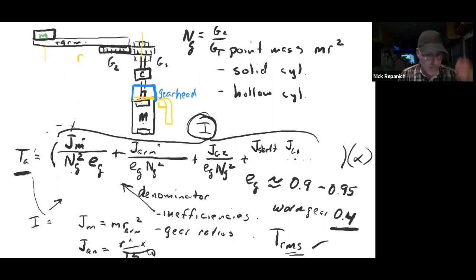I hate to use that word. I'm going to use RMS because it is not the average amount, but it is related to how much heat the motor is going to have to dissipate. So for some systems we got to go back and do this RMS calculation, and it's horrid. But at least it's an easy formula. It's just big to deal with.